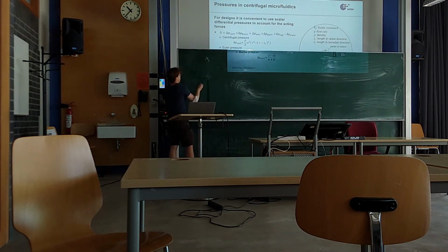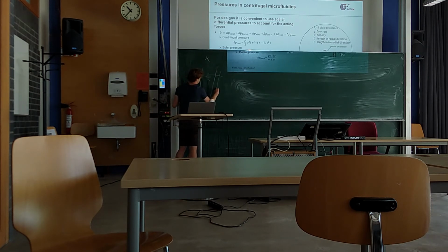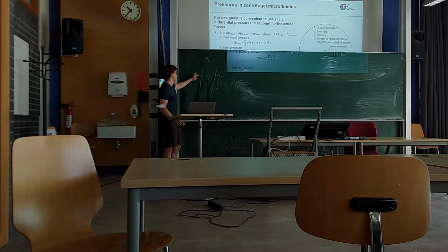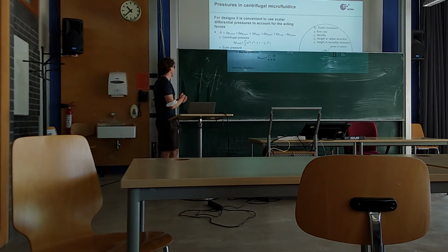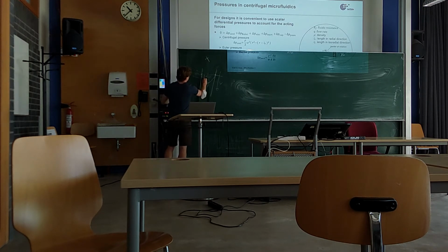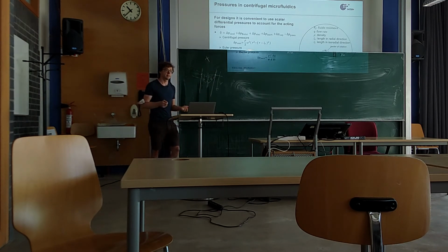So let's assume we have a radial channel. That's our velocity. What would you expect the velocity to be at the wall? Zero, right? Because the wall is fixed and the velocity will be zero. So how would the profile probably look like? Yeah, right. So once again you assume that the flow profile is described by the Hagen-Poiseuille law, and that's where you also get your resistances from.